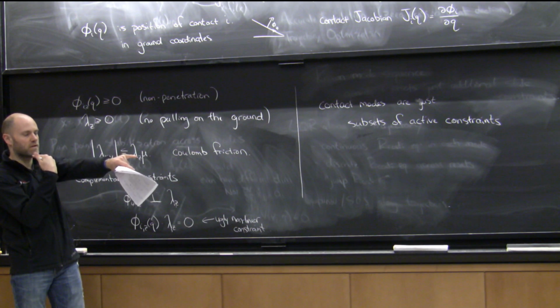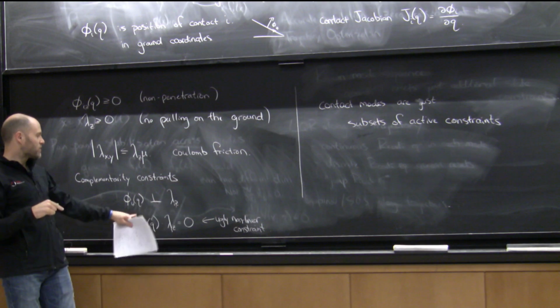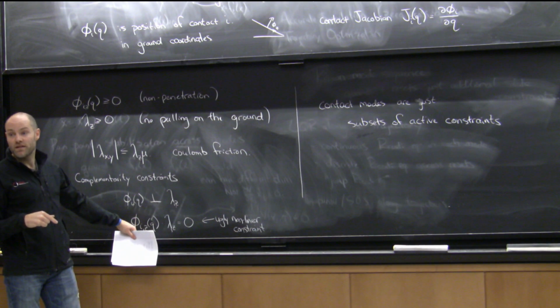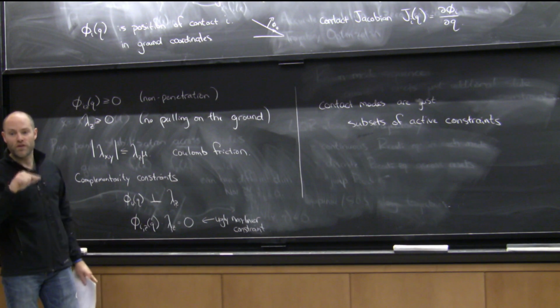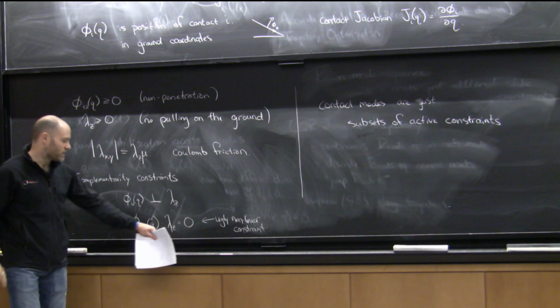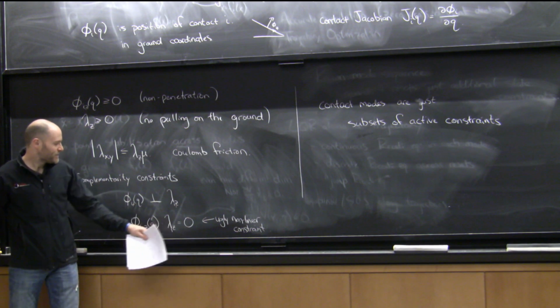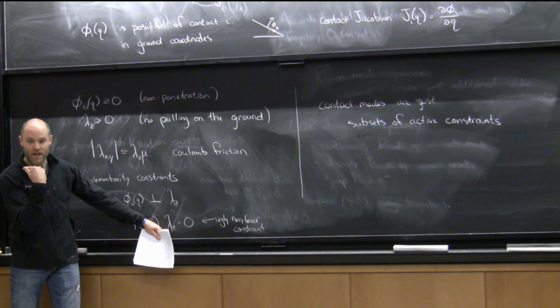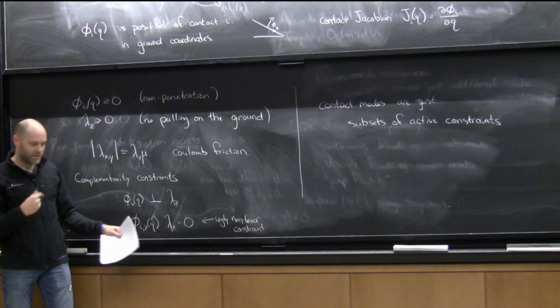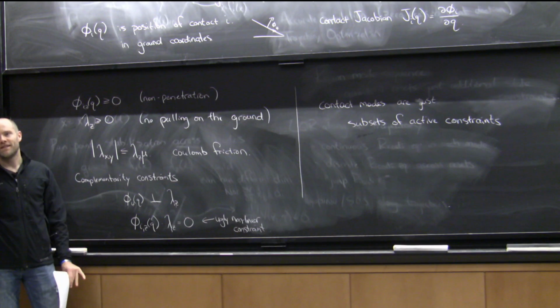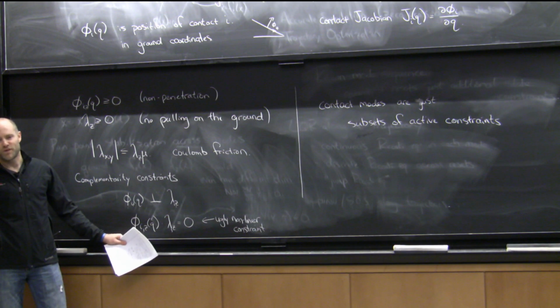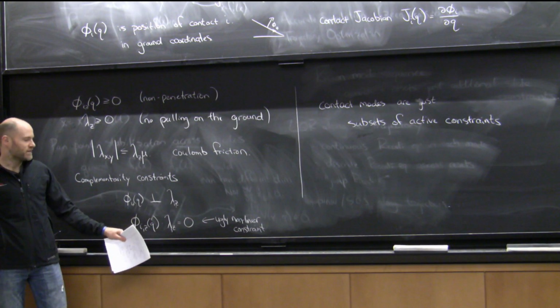You get another complementarity constraint that models whether you are sliding or not. Either you're sliding and your force is on the edge of the friction cone, or you're inside the friction cone and you're not sliding. That's way uglier to write and requires slack variables, so I won't write it down.